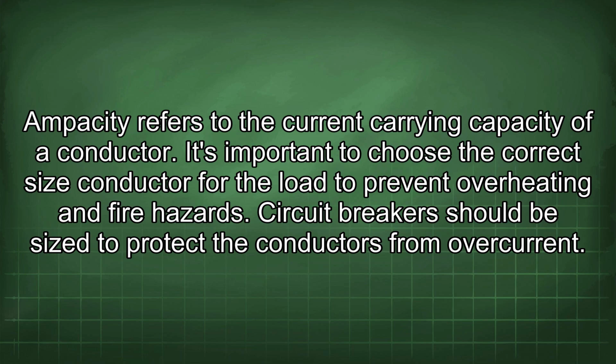Ampacity refers to the current carrying capacity of a conductor. It's important to choose the correct size conductor for the load to prevent overheating and fire hazards. Circuit breakers should be sized to protect the conductors from overcurrent.